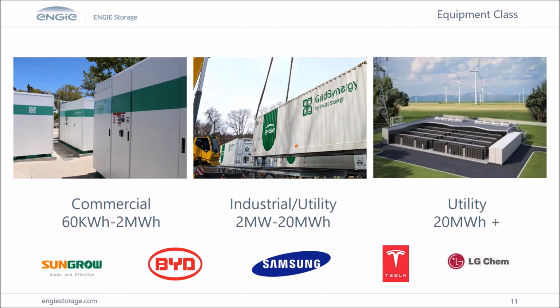So it's important to read the details of each and understand if they are best suited for your application, because someone using frequency regulation as the primary revenue has a very different configuration than someone using a 4-hour battery for long dispatch. You have to understand the difference between the uses and which system is optimized and is really going to fit your needs.